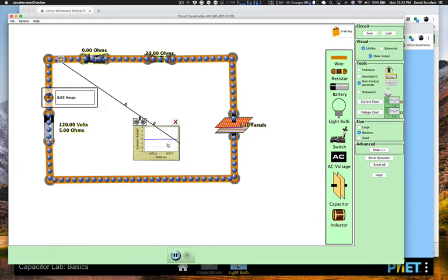All right, and as time goes on, eventually you can see the current looks to be approaching 0. And my capacitor is now finally charged. And that took a certain amount of time. It does not happen instantly. And it's owing to the combination of the capacitance and the resistance in this circuit, that time that it takes to charge that capacitor.